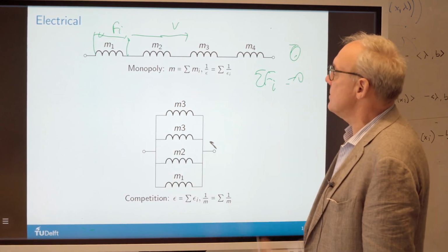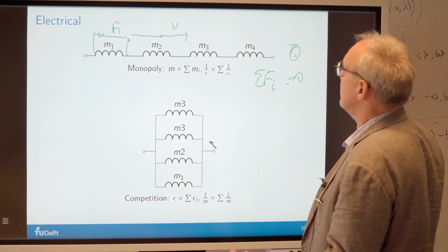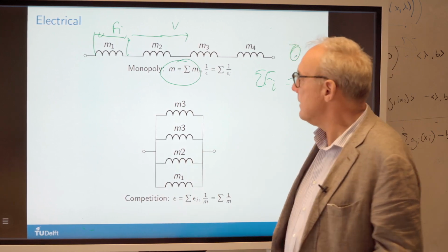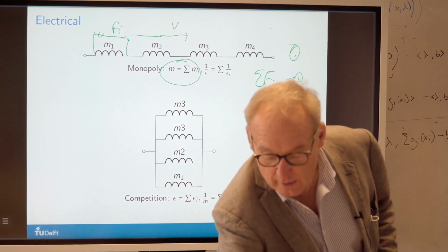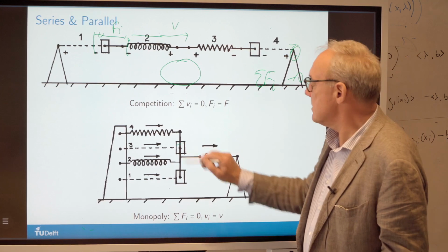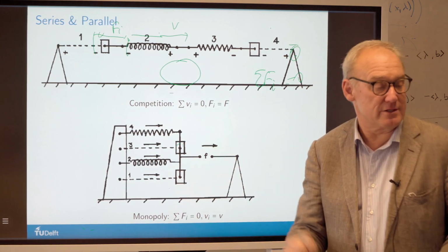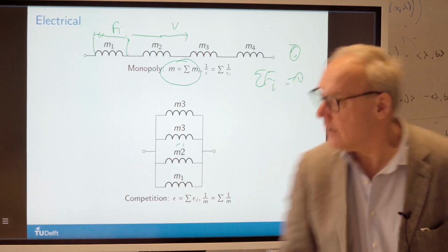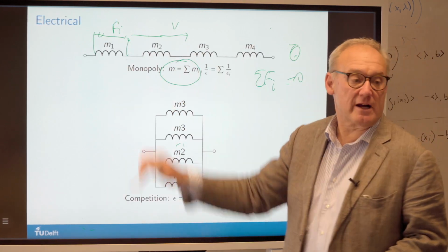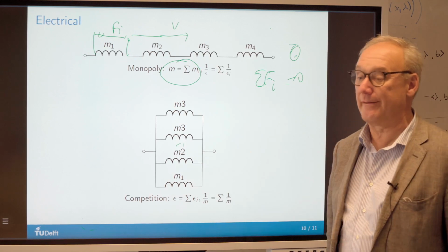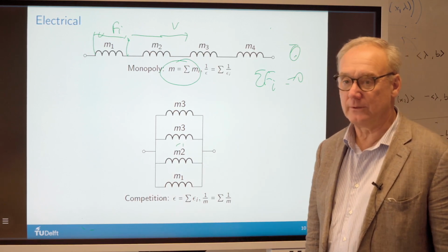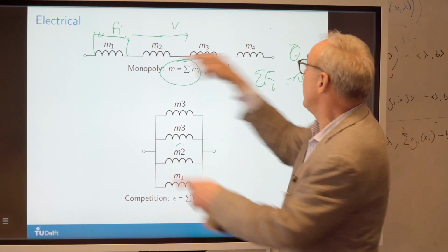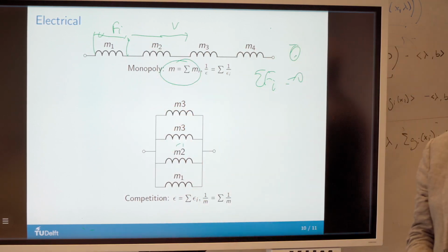You call the inductors the mass. You'll see that the effect really is that you're just summing the masses, and this is what I believe Ruma was pointing out on this one over here. You can just add these two masses, because they're just linked together. Here, you can add all 4 of these inductors because they will push through the same current when you put that big voltage drop over it. That is a better way of reasoning.